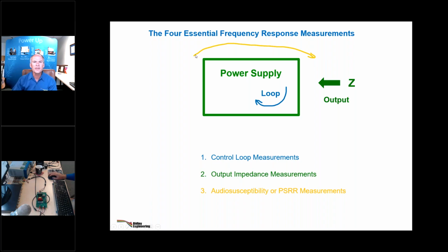And that's had an interesting history. As I said, in the beginning, everybody did it all the time. And then, as I hope we get to this measurement, when people went to current mode control, it became so low you couldn't measure it anymore. It's just below the noise threshold of any analyzer that you have, so you can't see it. So people built current mode for 10 years and 20 years, and they didn't question why they should do current mode. They just knew that, and everybody kind of stopped measuring the audio susceptibility anymore.